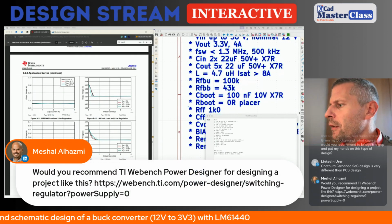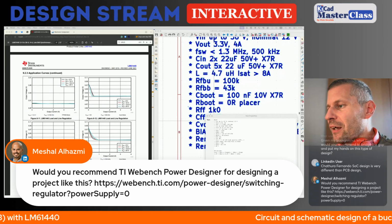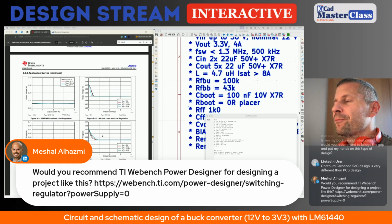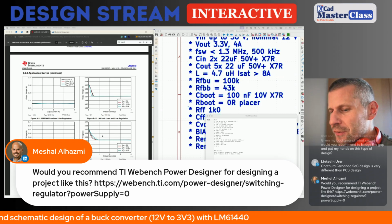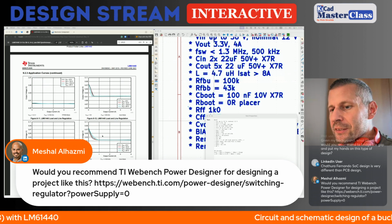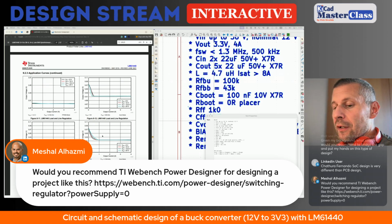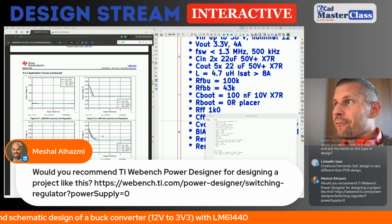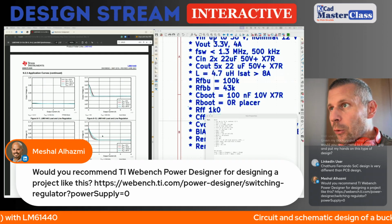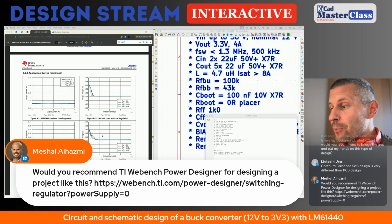Yeah, we have the comment. Yeah, for sure. This time I want to go through the datasheet, because the disadvantage of WEBENCH is that people who are inexperienced with circuit design can't see the equations and formulas behind it. So of course, everyone, you can choose WEBENCH, but you have to follow the values WEBENCH will give you. If you start with the datasheet and your own calculations, you will get your values, and then you can compare the values with the WEBENCH Power Designer.